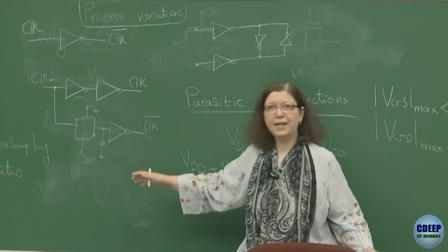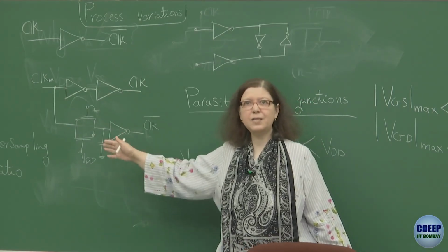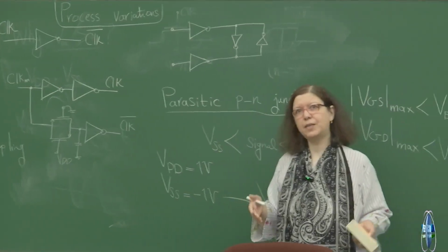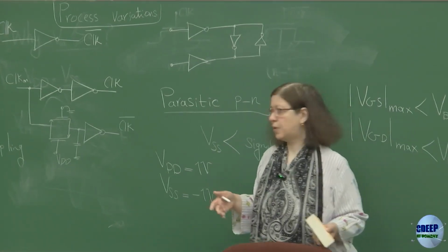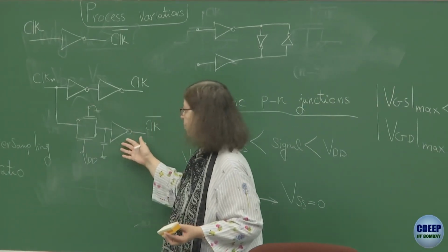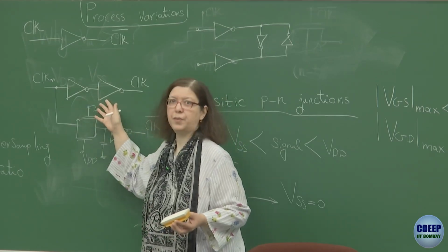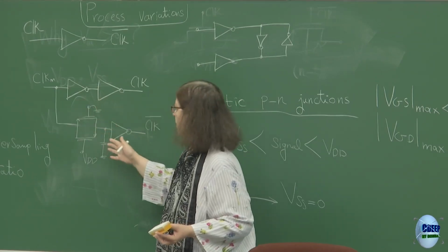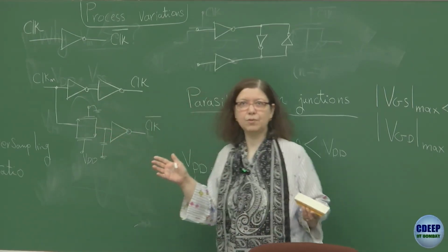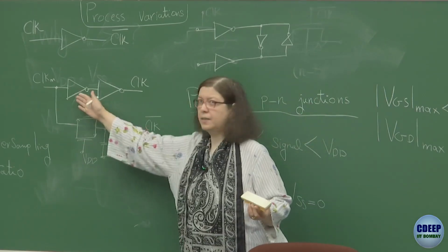So therefore, it's like you have a track and hold which is always on, of course, here. So it's like an RC circuit. You put an RC circuit, but R is made by transistors. So you are trying to make the delay of this path, because this has 2 NMOS, 2 PMOS, and this has 4 NMOS, 4 PMOS, likely to compensate. You can adjust values so the delay of this path is exactly the delay of this path.